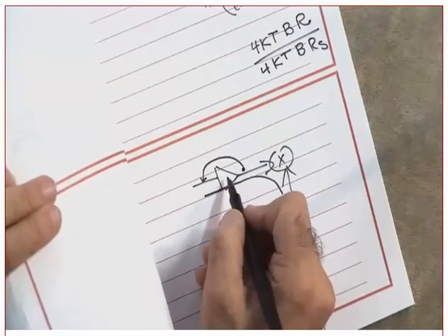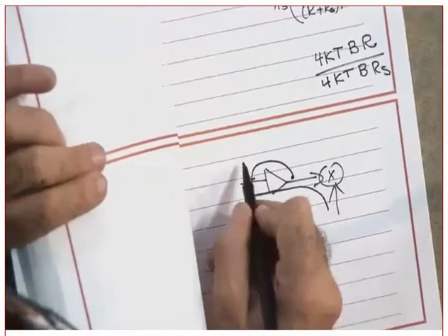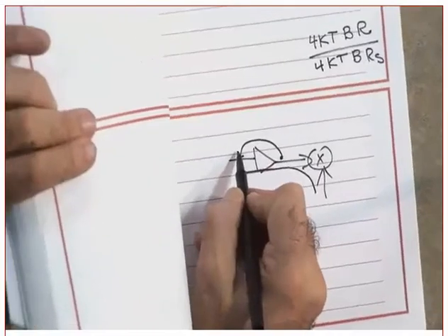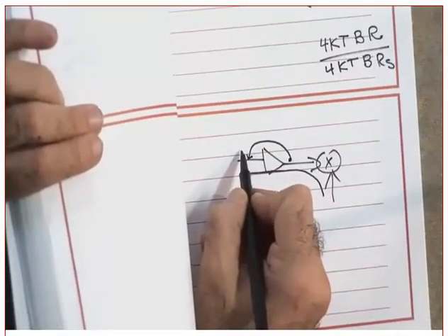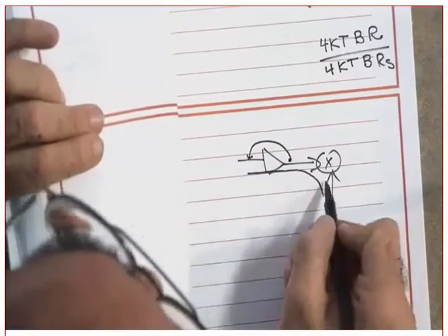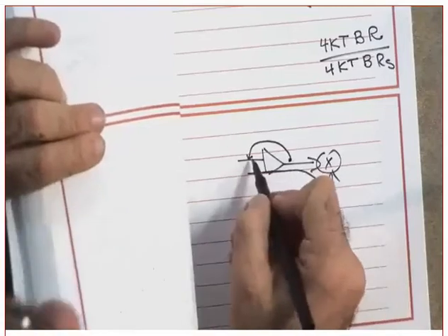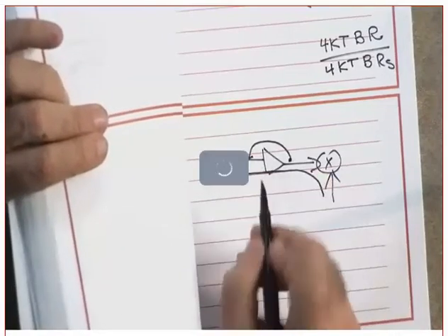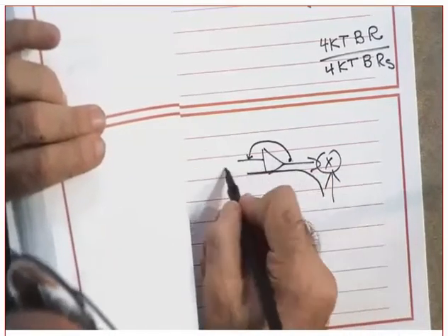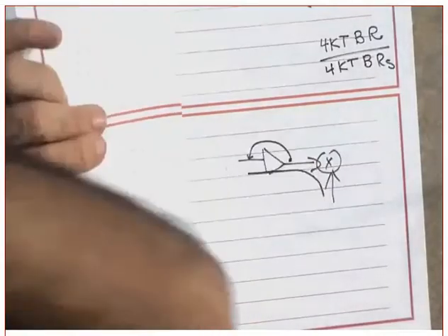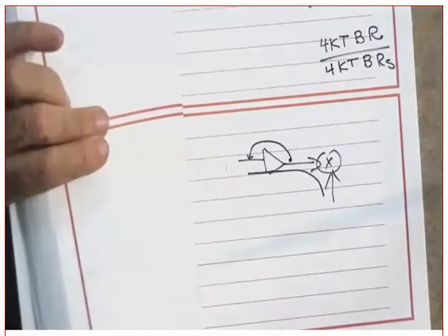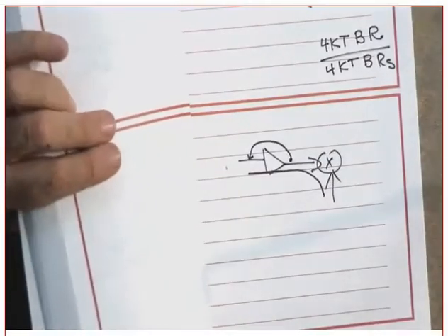Now, for the superheterodyne, this is not a big deal. Why? Because in a superheterodyne, the local oscillator is not the same as the RF. But for the homodyne, is it a big deal? It is a big deal. Now, let's assume this one is different. Isolation is still a big deal. Why? Because this one might go to the antenna and it will interfere with the people who are operating in the adjacent channels. Did you lose me?